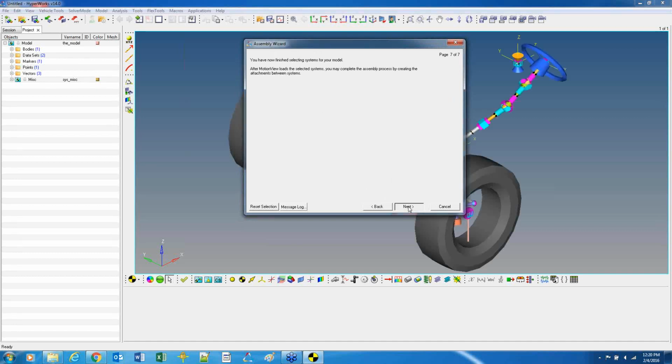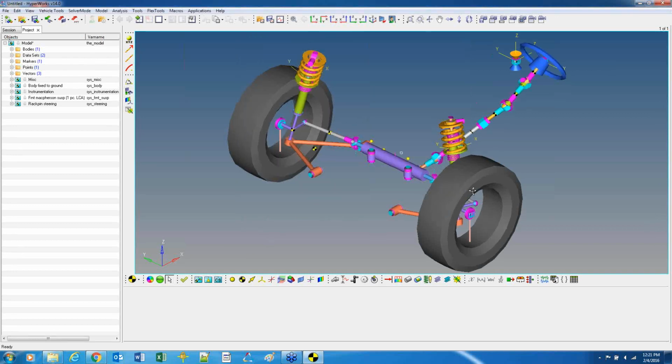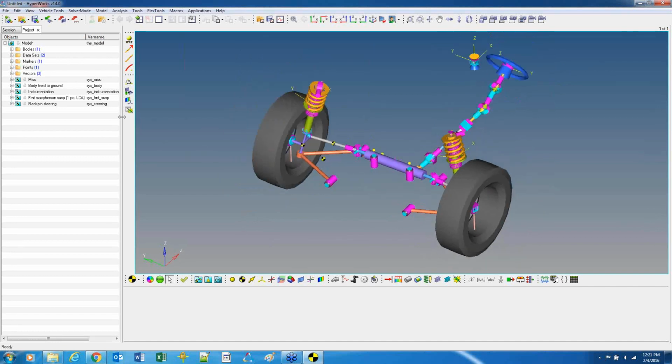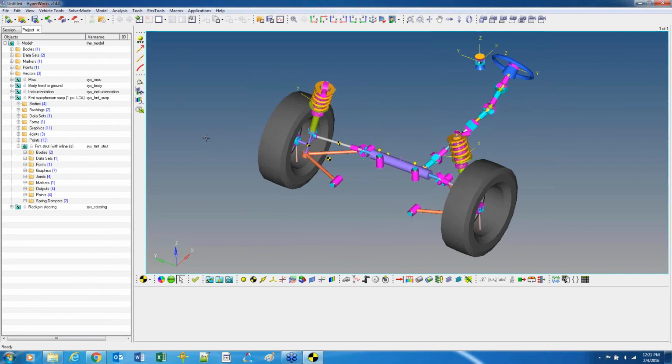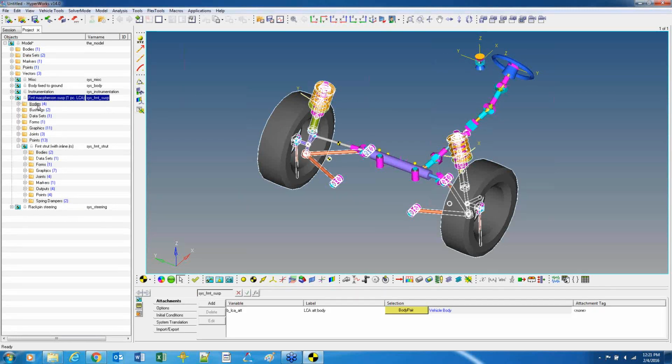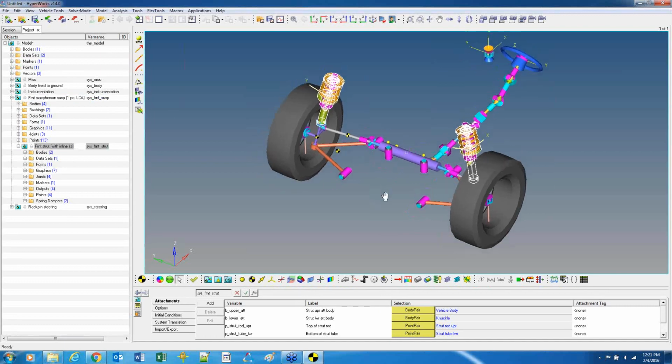So I'm going to take some defaults, and what you're going to see is that it takes those answers that I supplied in that wizard and goes into the big library and extracts the various systems and subsystems that I asked for. In fact, what you'll see now on the left, since I have a model instantiated in the pre-processing window, is that it has actually built up a hierarchical model. So this is one of the abilities that comes with this modeling environment, in addition to just the automated build of the topology originally, is the whole layout and modular approach to it. So these blue areas are called systems, and they're containers for the collection of atomic entities as well as other systems, and hence the hierarchy of the model. But we do that for you when you select from the library.